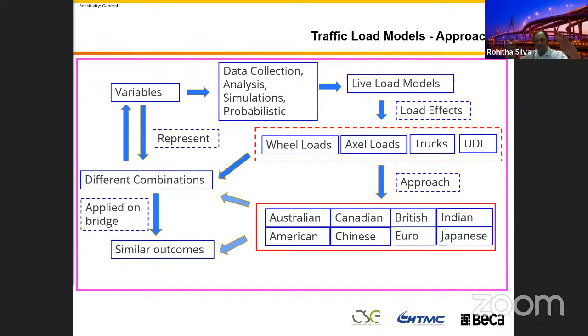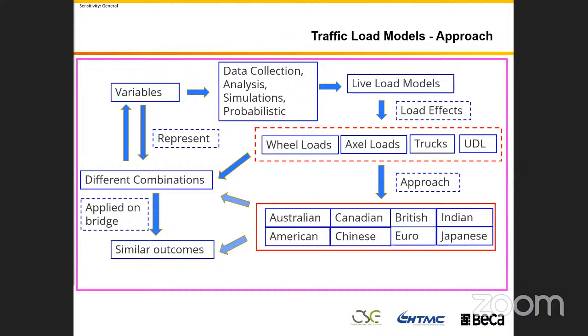When we put a truck load on a bridge of that length, what would be the uniformly distributed load, if we do all this very simple calculation. In the slide, I explained the dynamic magnification factor, but each design standard defines the relevant magnification factor. You don't want to use that one as a baseline. This is just an example. Is it clear? Okay.